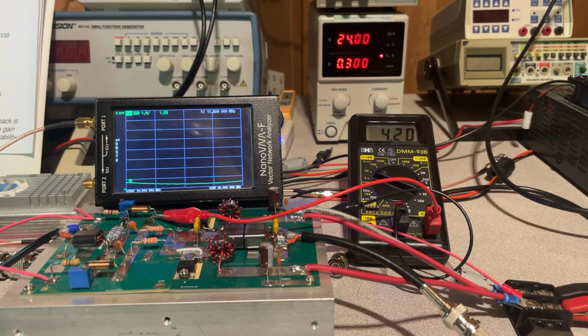Okay, so you can clearly see that MOSFETs are voltage devices, not current devices like a bipolar transistor. So it's very easy to bias these with a simple voltage divider. And as we increase the gate voltage above the threshold in the specification, we start to see that the drain current increases.